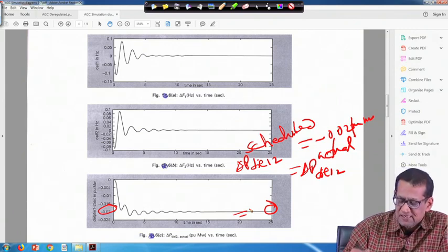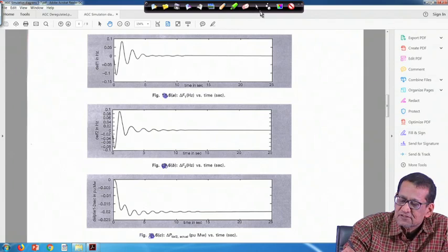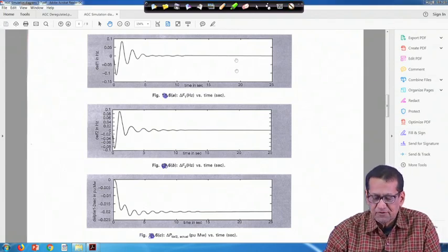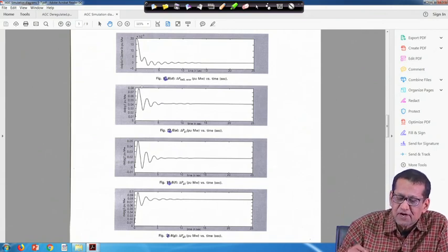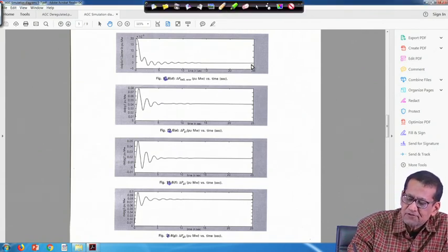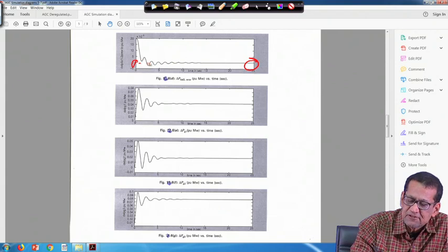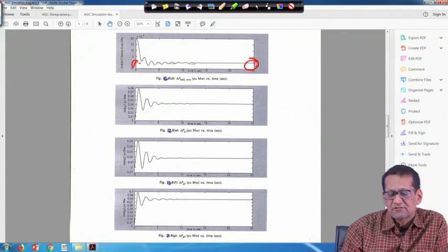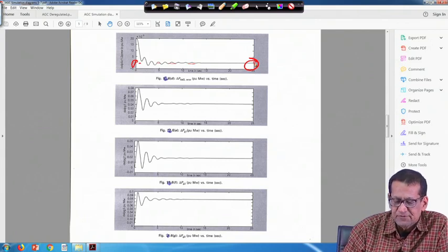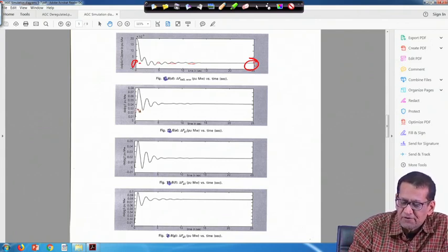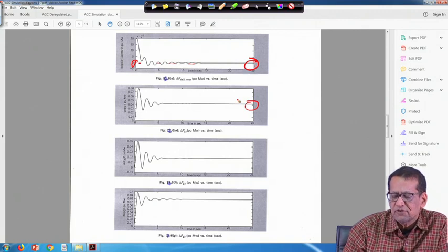So, this is the result, right. Similarly, if you go to the generation, this is delta P tie 1 2 error, which at steady state will be 0, because this is the 0 line. Now, delta Pg1 per unit megawatt is 0.042 at steady state.